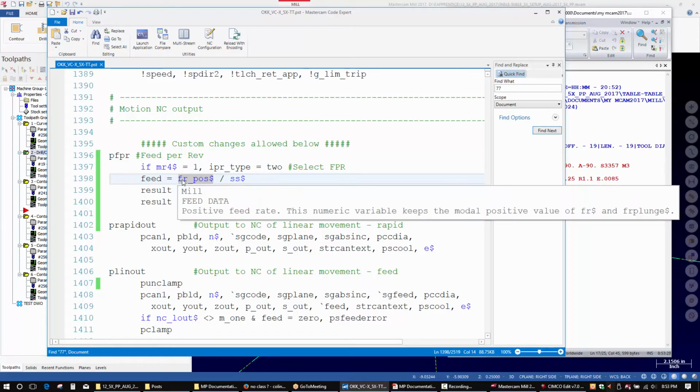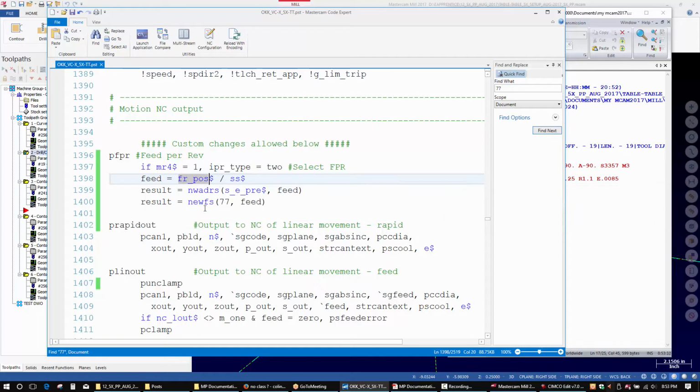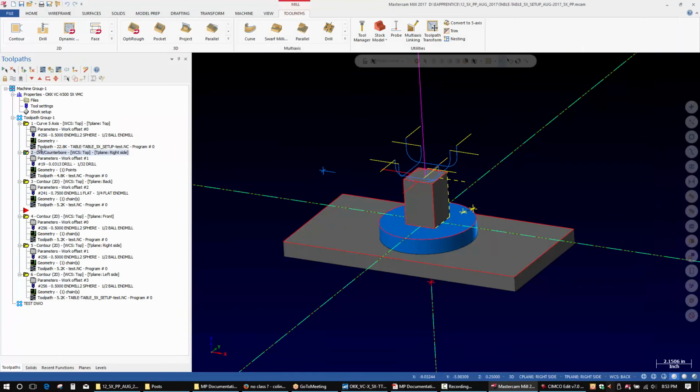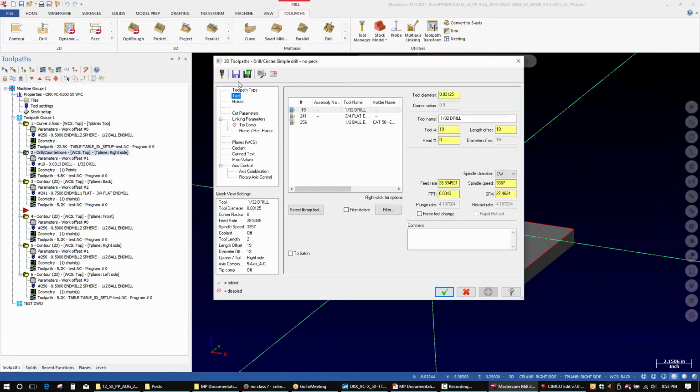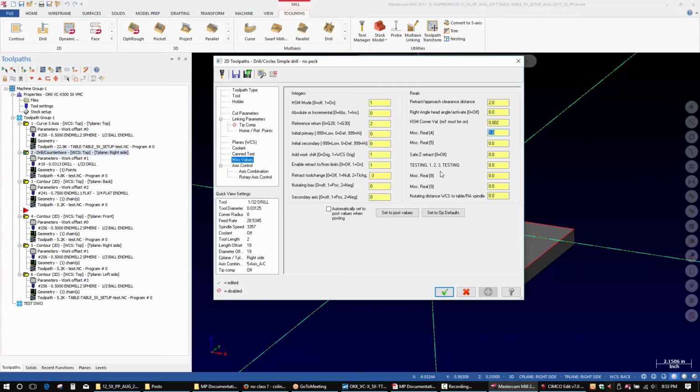So that being the case, because the feed rate that we enter in the dialog is already rounded, we'd have to get a little bit tricky in order to do that. So for example, right now we're just putting in 1. Well, instead of 1, let's put in the actual feed per revolution value we want. So it rounds it off to 6 places. Yeah, at least we can get up to 6.